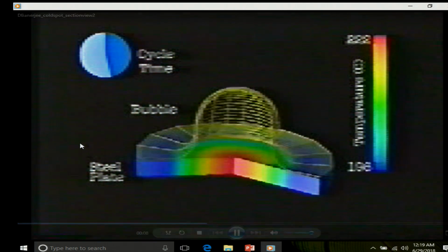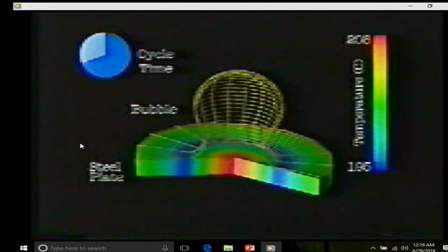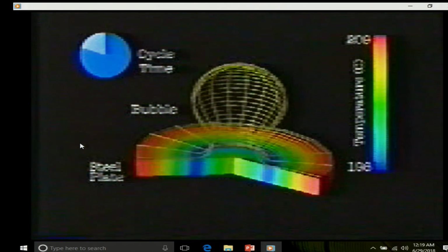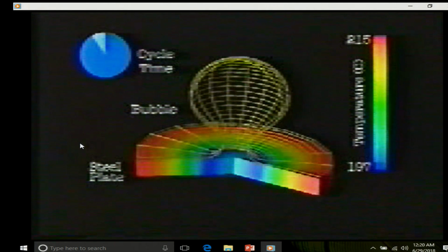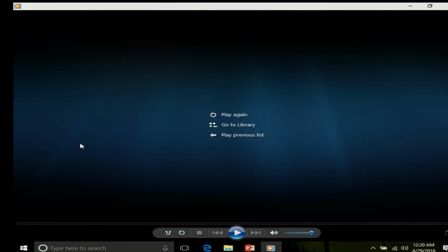What you see is a vapor bubble that is growing. This is the heater substrate, and remember I plotted those delta functions. Wherever my liquid-vapor interface touches the surface, or in film boiling wherever the vapor film thickness is the lowest, that is where I get the maximum heat transfer, and the point where I get the maximum heat flux is where the cooling occurs.